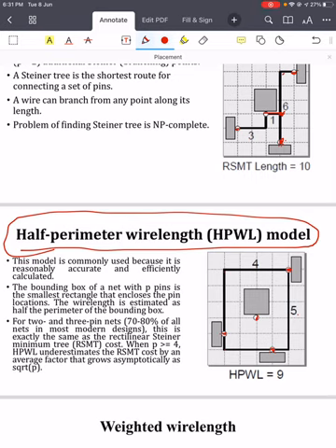Most of the design consists of these 2-pin and 3-pin nets. 70 to 80% of all the nets in modern designs are usually 2-pin and 3-pin nets, and this is exactly the same as the rectilinear Steiner minimum tree cost. Well, not exactly, I won't say it is exactly the same, but it will be a comparable estimation.